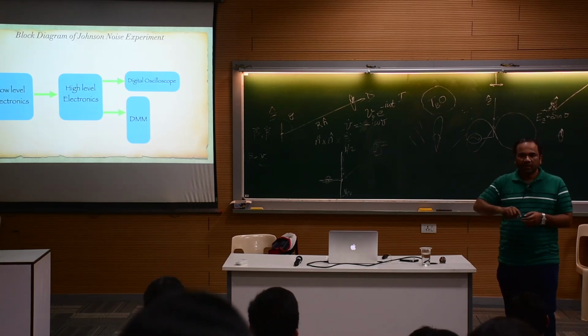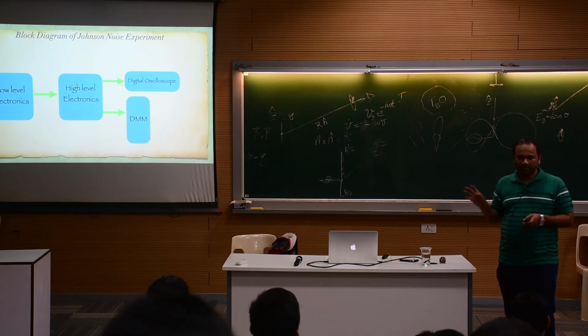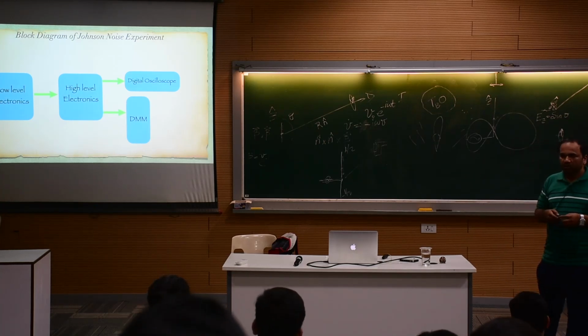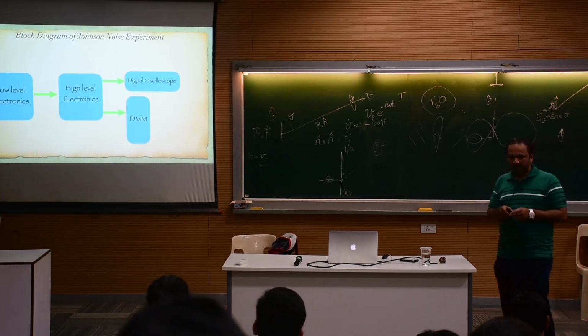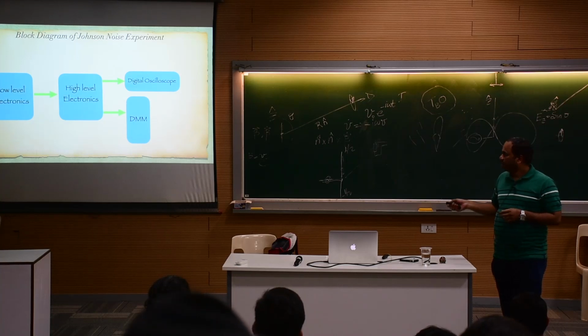We can select different values of the resistor, and we can study noise which is generated by that resistor at the output. In low resistance we could do that, and there are amplifiers, but those are fixed. There are two amplifiers, one with a gain of 6 and one with a gain of 100. So the total gain will be 600.